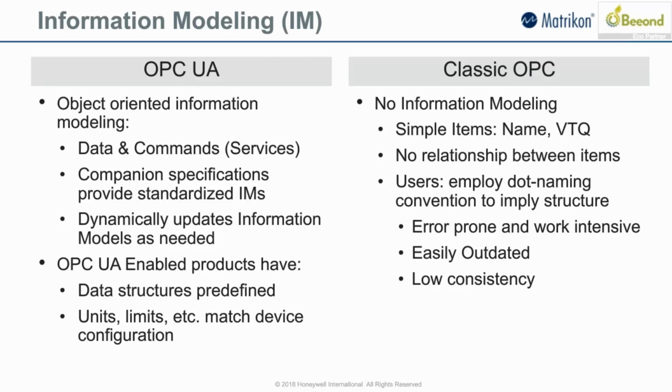So of course, your mileage will vary. If you're talking about generic PLC type applications, well, you can still set up models within that, but of course the PLC vendor won't be able to give you a model because they don't know what you're going to use it for, unless it's a specialized PLC. But still, you either have the flexibility to set up that model, or if it's a purpose-made device, then it can already have all that set up in it. So huge difference between OPC UA and classic OPC there.